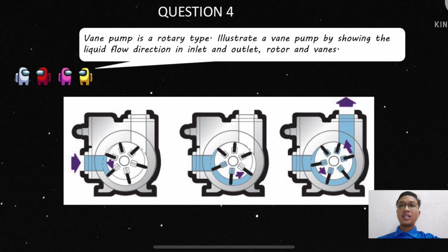And the last, as the rotor continues around, the vane sweeps the fluid to the opposite side of the crescent, where it is squeezed through the discharge hole of the cam as the vane approaches the point of the crescent. Fluid then exits the discharge port.